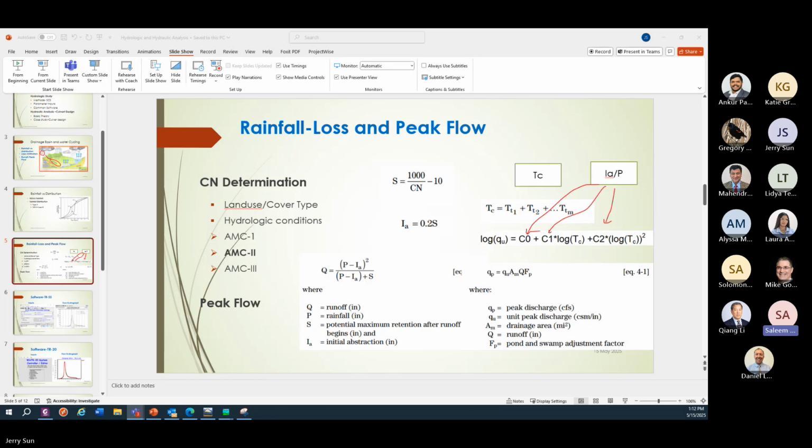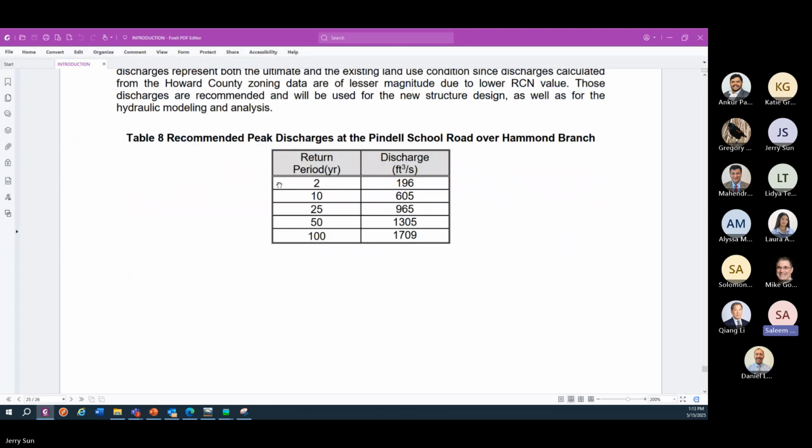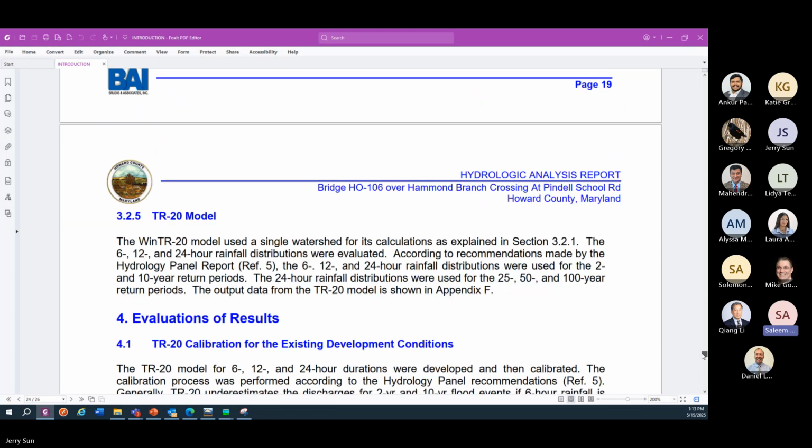So the best methodology, when we have these kinds of models, is that FEMA or other regulatory agencies, if there is available data like a stream gauge station, want to see that you go back and get the real historical rainfall data, if available, run that model, and route that discharge all the way to that stream gauging station.